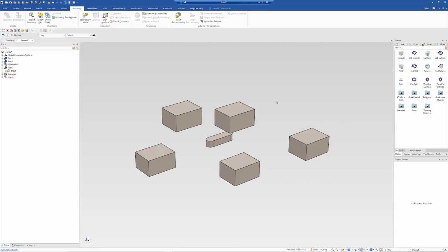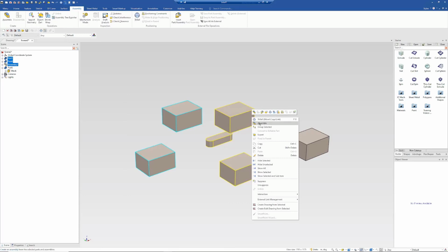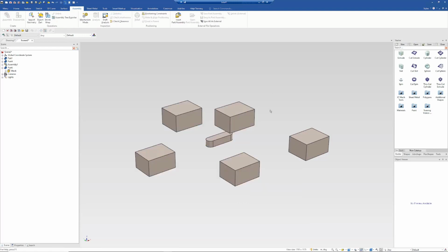In previous versions of IronCAD, you had the ability to use a box selection filter to allow you to select multiple items at the same time. With this box selection filter, you can assemble all the parts in a scene, move them all with a triball, group them, export them, delete them, many other things.